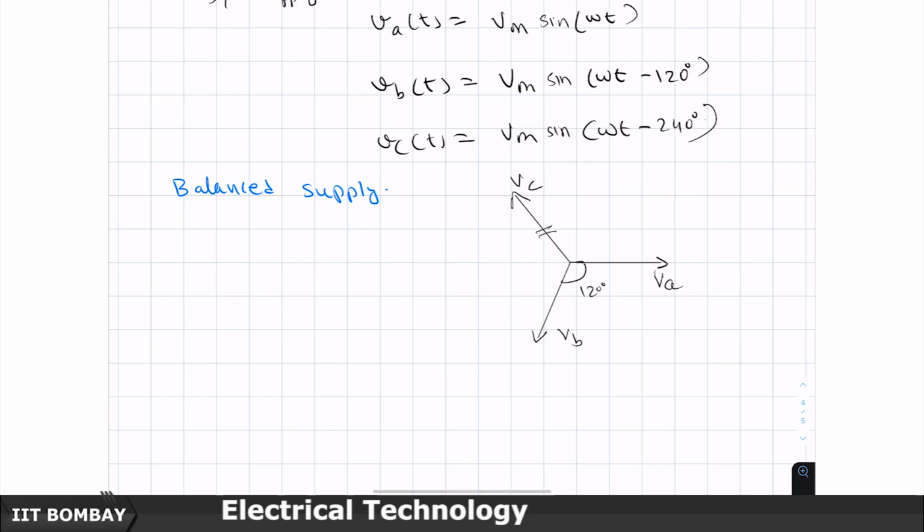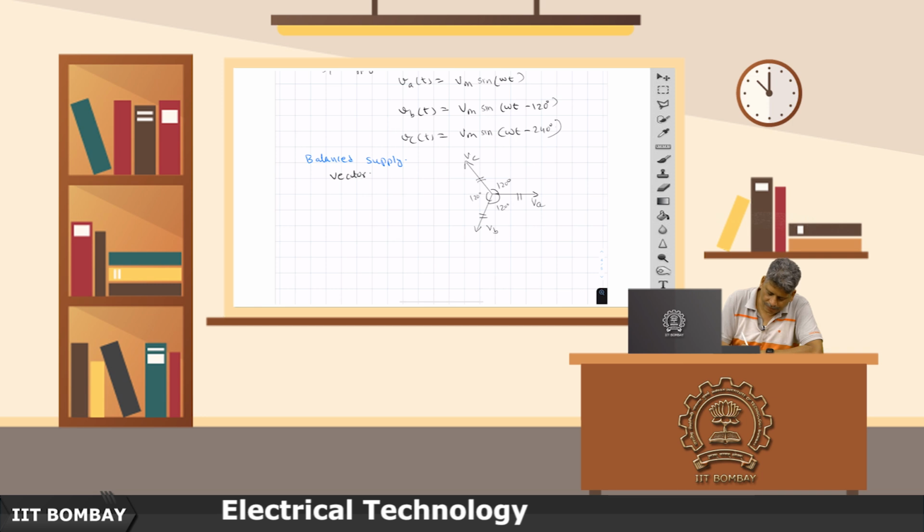They are equal in length and 120 degrees apart. They are vectors basically, but because we are dealing with three phases, these vectors are called phasors. But indeed what we just mean is that they are three vectors equal in magnitude displaced 120 degrees in phase. This is fine. You will see why this is done as we proceed.